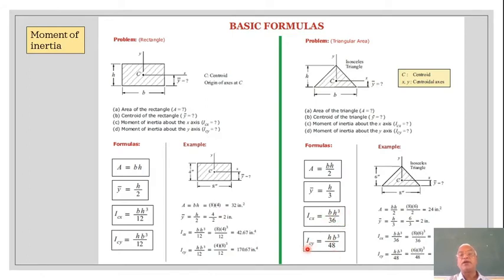Then ICY, because it is an isosceles triangle, it will be directly given. Otherwise you have to break the triangle into 2 parts and then work out. This is not a ready-made formula for a general triangle. I'll make you understand. Suppose there is a triangle something like that, which is not isosceles. The centroid will be approximately somewhere there.